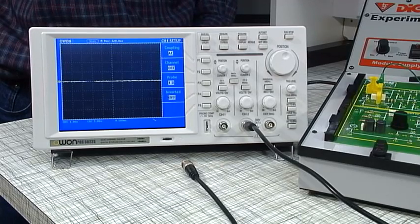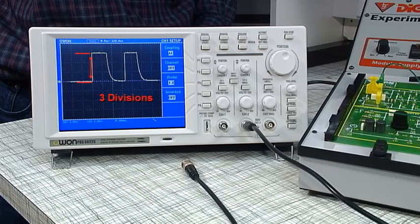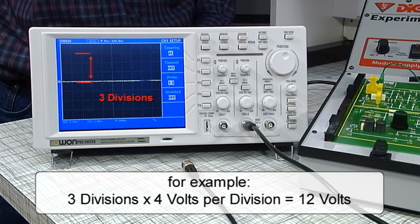An oscilloscope can also be used to observe a changing DC voltage. For example, the charging and discharging of a capacitor can be viewed on the display screen. During charging and discharging, the trace will move up and down the screen. The voltage value can be calculated by counting the number of divisions or, if necessary, subdivisions between the reference point and the new location of the line. When this is multiplied by the amplitude scale, the voltage will be obtained.